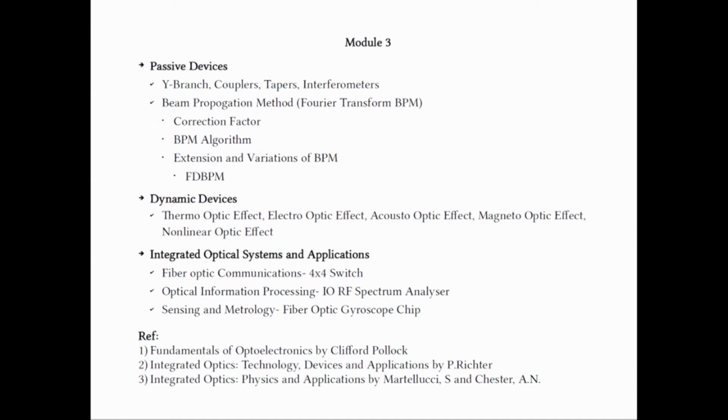So, then we looked at some optical systems of application of all these devices that we have studied. In particular, we have looked at an example of a fiber optic communication system where we can make a 4x4 optical switch by using 5 directional coupler switches. By configuring these directional coupler switches, we can get many connectivity options. We can represent that in the form of a matrix. Many combinations are possible, but of course not all combinations, which could be extended by going for a higher number of optical switches and configuring in a different way. This is one of the direct applications or uses in practice.